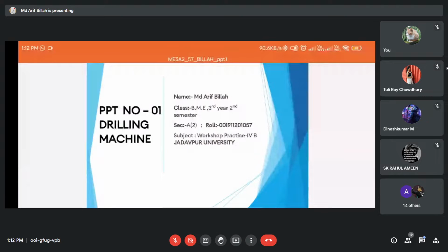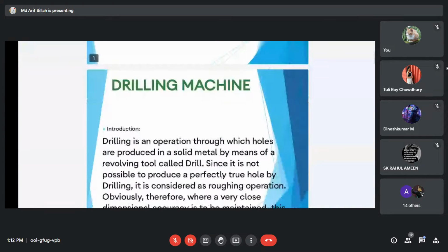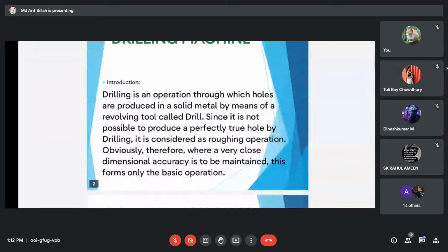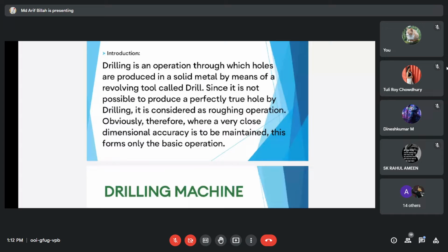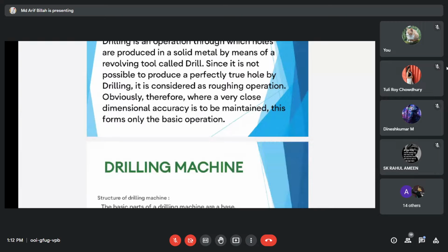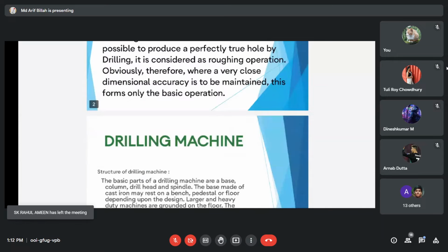Okay, sir. My name is MD Arif Billah, roll number 57. I am going to present on the drilling machine. This is the drilling machine introduction. Drilling is an operation through which holes are produced in solid metal by means of a revolving tool called a drill. Since it is not possible to produce a perfectly true hole by drilling, it is considered a roughing operation. Obviously, therefore, where very close dimensional accuracy is to be maintained, this forms only the basic operation.